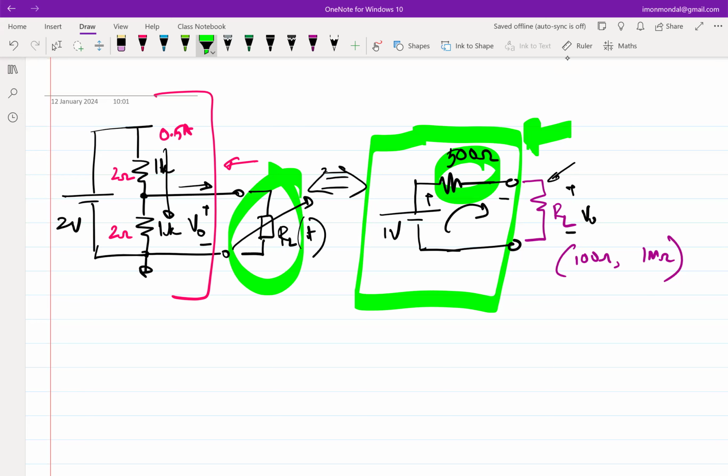Equivalent is only meant when the load resistor is connected. That statement is correct, but how is it related to this question? Excellent. The Thevenin equivalent only says that the external behavior is the same, so whatever you are observing at the port doesn't change. It doesn't make any statement about whether the stuff inside the box will be identical. It's a model.